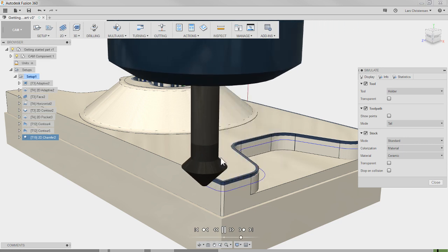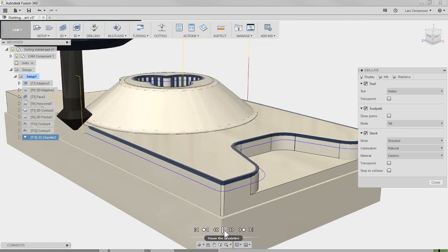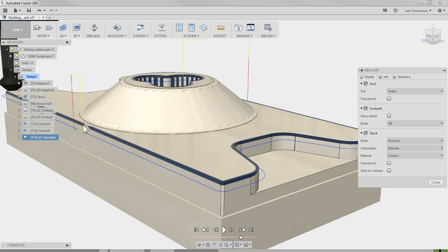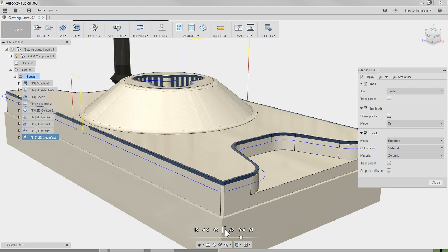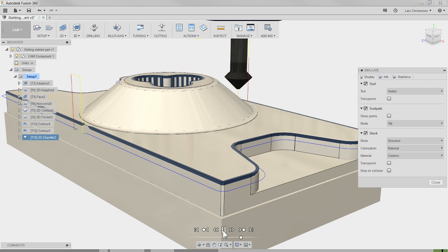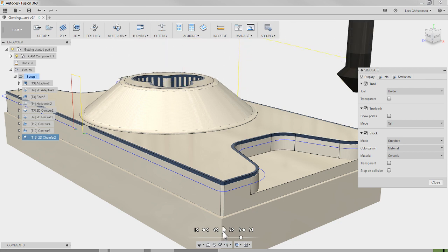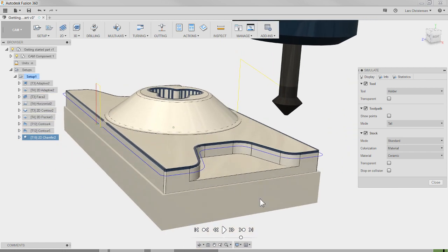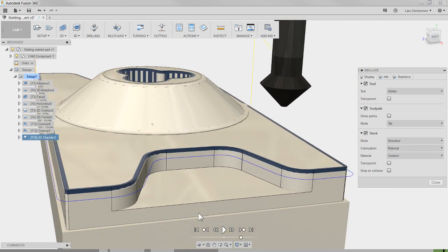So it's going to chamfer around. This is actually a pretty big chamfer. You will see also that it stops right there because it sees this area and is making a pretty big chamfer. So that's why it's avoiding that, because it knows it cannot touch that. And that's the same thing it's going to do when it comes down here to the end of this. It's smart enough to know, and I'll owe somebody on the development team a beer for this.